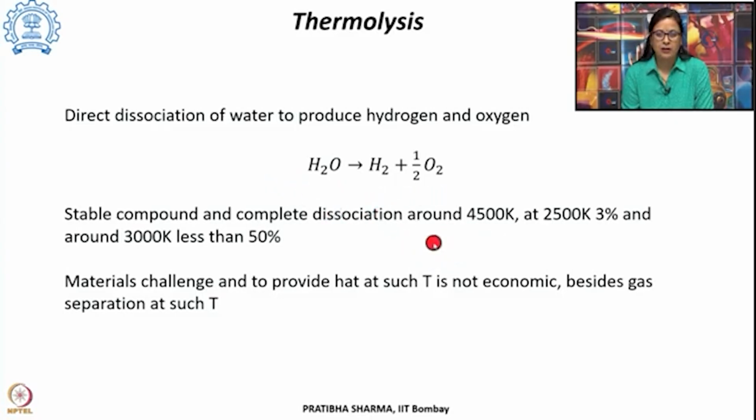and that will lead to many challenges, in terms of the materials challenge to contain that heat and to provide that heat at such a high temperature. Definitely it is not economical. Besides, at that temperature when we are getting hydrogen and oxygen, the separation so that it does not form an explosive mixture is also essential. So if we want hydrogen from water using this single step thermolysis process, it has several challenges.